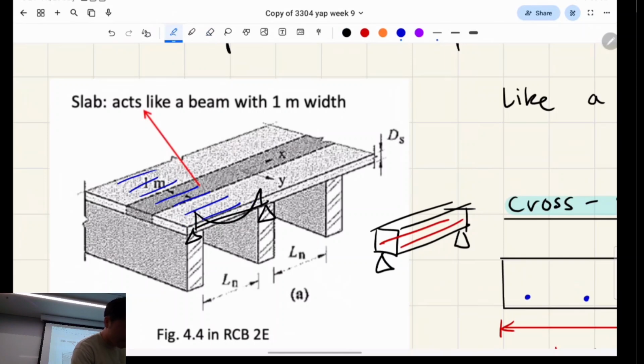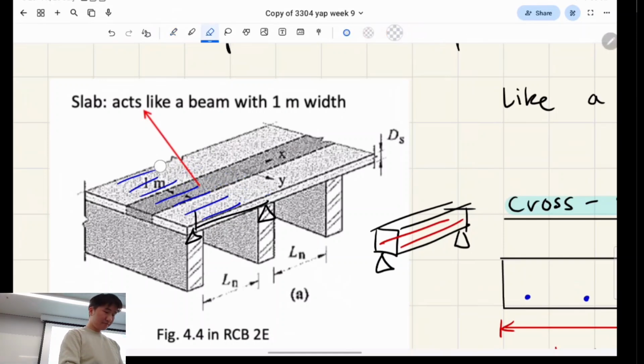The compressive rebar is where there are your hogging moments, so that will sit on the top half of the slab where there's a support. But it's all tensile rebar. We don't have compressive bars. I don't want to say that, because in actual slab design we do have compressive bars, but it's not the primary steel taking on those forces, so we don't really focus on that in this course.